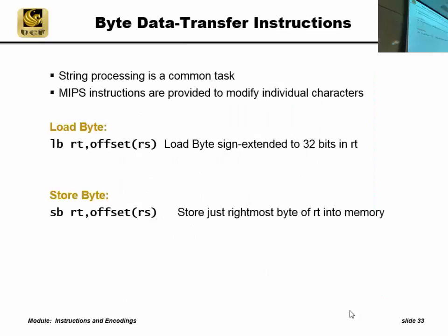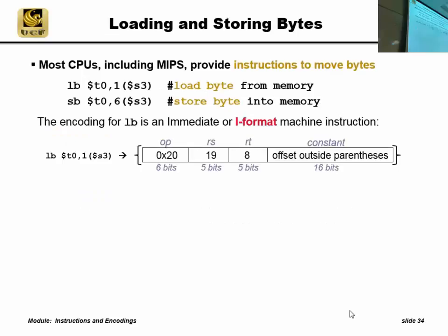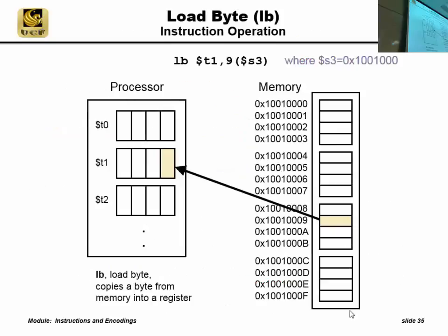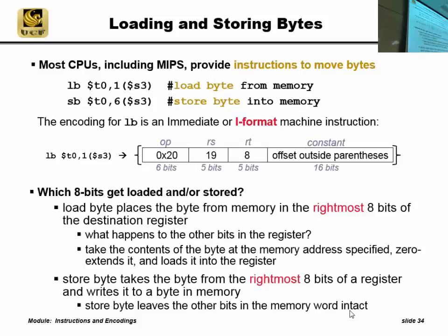Okay. So let's look at the instruction to access 8 bits at a time, knowing that it's going to be transferred into a 32-bit register with sign extension. That's a load byte. When do we want to use this? So we're accessing characters of a string. Store byte is the same as store word. It's nothing new. It's the same syntax, but it's going to move 8 bits at a time instead of all 32. So here's the syntax, and then we're going to show you the actual byte. So here's LB and SB, the syntax. The register, offset, and base is the same as load word.